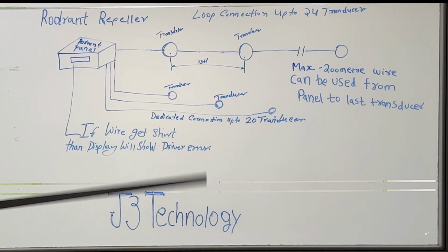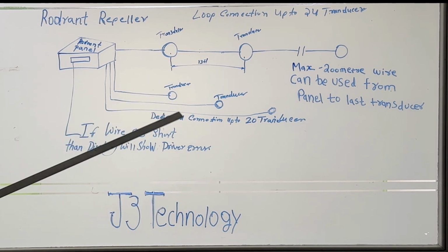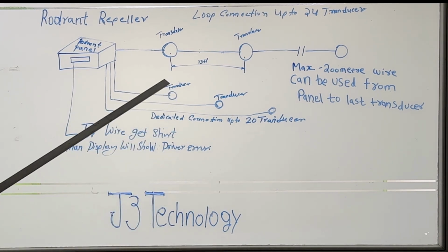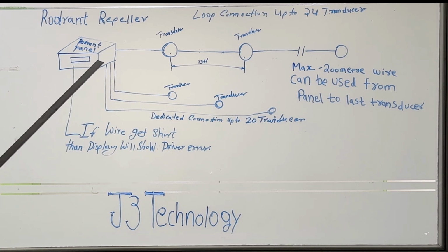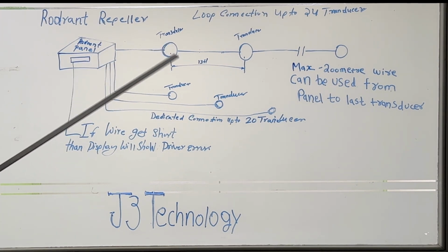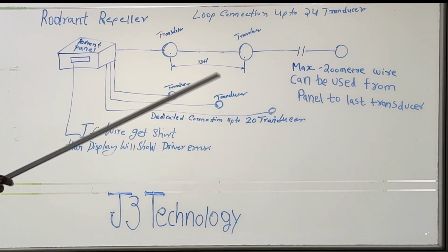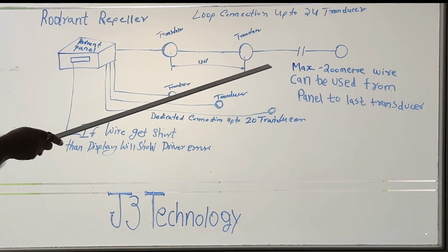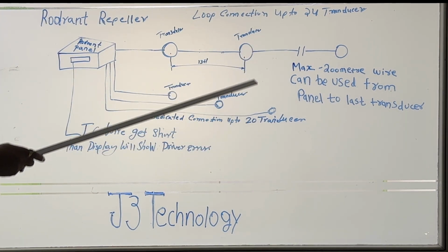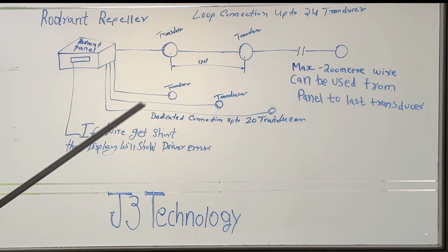So you have to do this practice monthly, as annual maintenance and monthly maintenance, by pressing the menu button four times and checking each individual transducer to see whether the audible sound is coming or not. That is the perfect way to check whether the transducer is working or not.